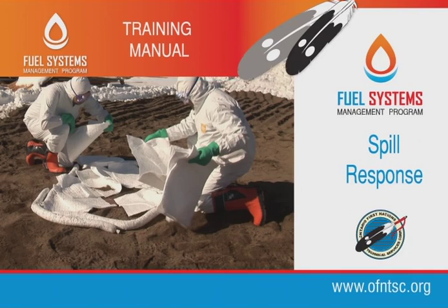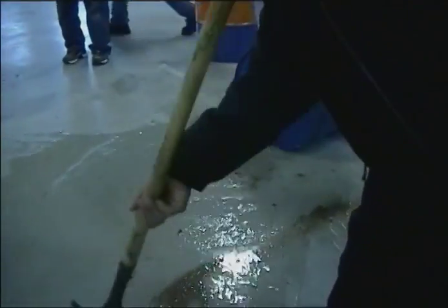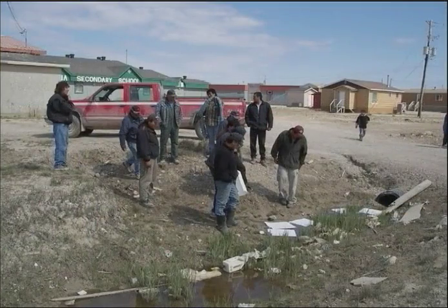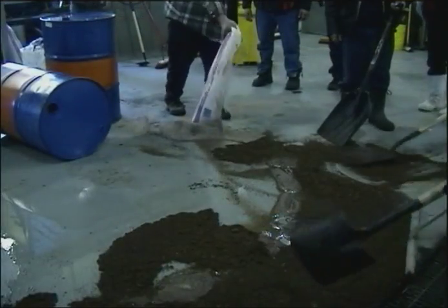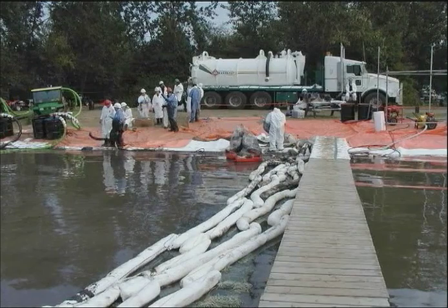Spill response. You may be called upon when an uncontrollable release of petroleum liquids has escaped into the environment. You should be prepared to try and control the substance by stopping the source, minimizing the extent of the contaminated area, recover the spilled material. Each spill differs by time of year, amount of release into the environment, and local land use.